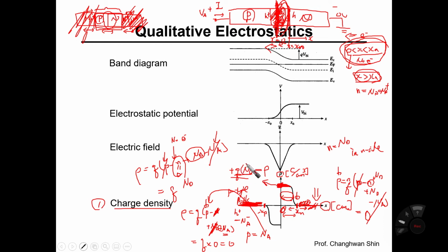Depending on the doping concentration, the charge density in the depletion region can be determined. Similarly, the depletion region on the P side can be understood simply. So what is this value? Yes, only ionized acceptors are left behind because all the holes have diffused toward the N side.